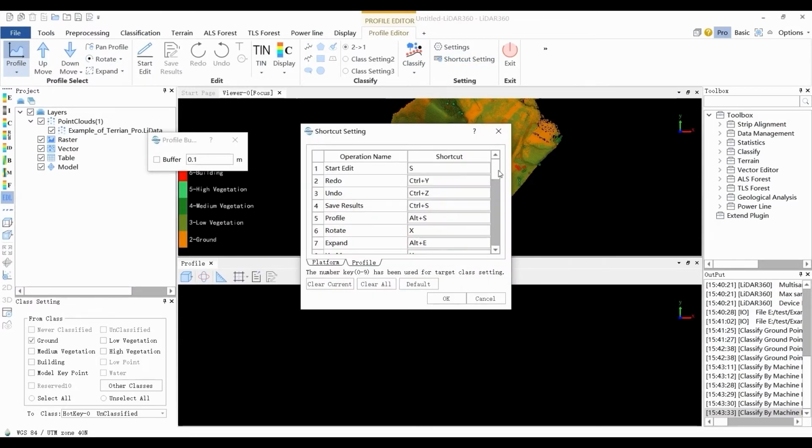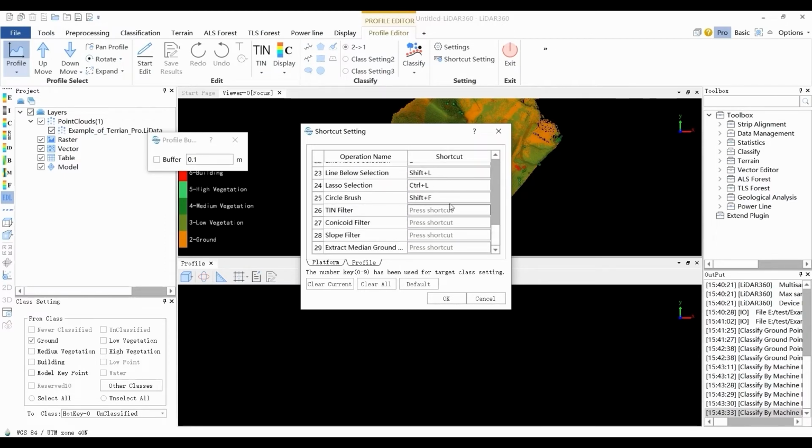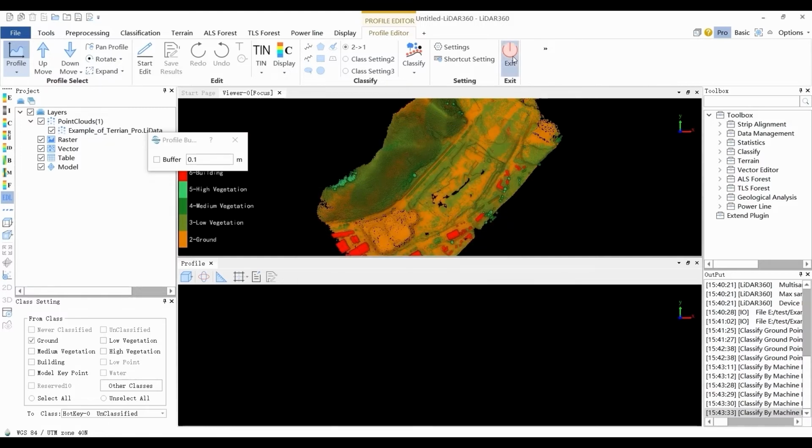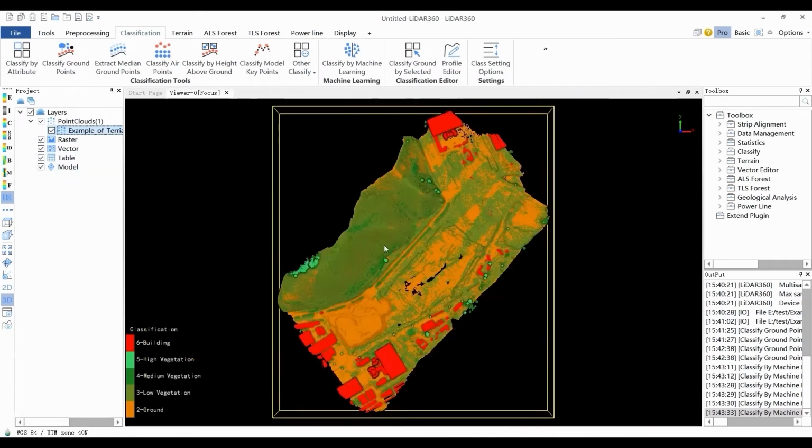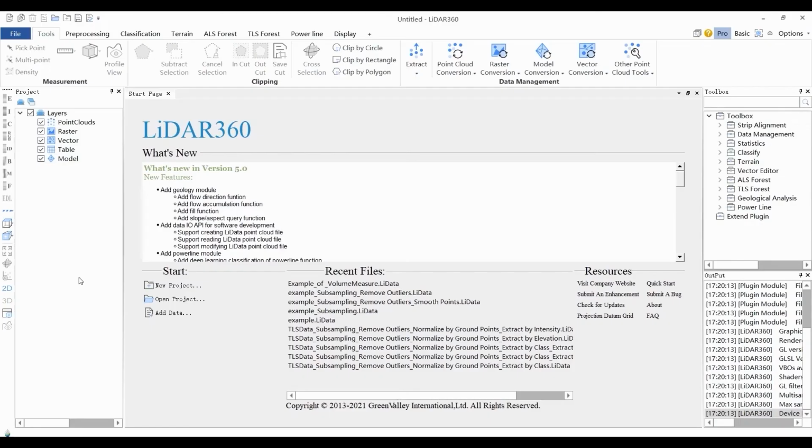This section will further show you the volume measurement options available in LiDAR360 in its workflow. If you open this tool, the options of volume measurement methods will pop up. If volume measurement is selected, users need to select the measurement area by clicking the mouse. If measurement area is defined by file, users can load the file with measurement area information to measure the volume of the target object. It is suggested to adjust the window to top view before the tool is used.